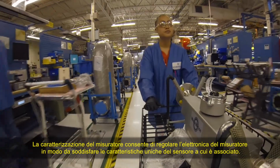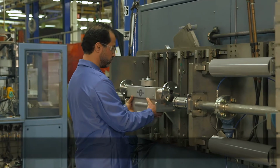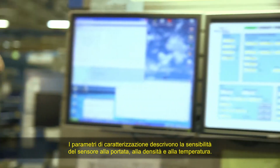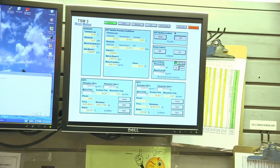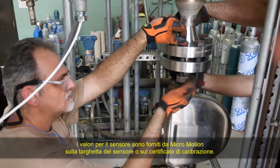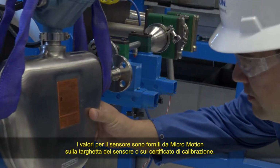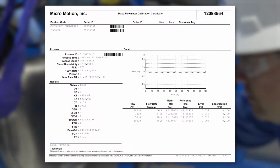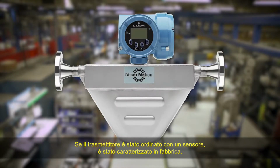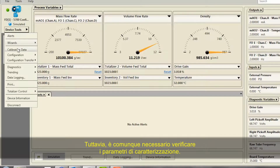Characterizing the meter adjusts the meter electronics to match the unique traits of the sensor it is paired with. The characterization parameters describe the sensor's sensitivity to flow, density, and temperature. Depending on your sensor type, different parameters are required. Values for your sensor are provided by Micro Motion on the sensor tag or the calibration certificate. If your transmitter was ordered with a sensor, it was characterized at the factory. However, you should still verify the characterization parameters.